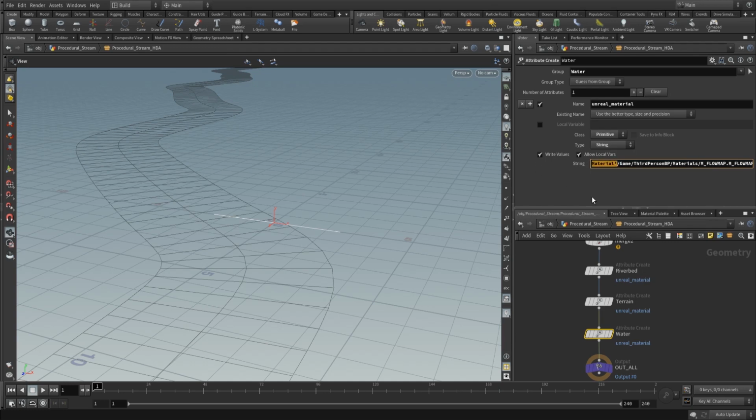I'm going to delete the first part. It's called material. Delete the last tip. And now this geometry that gets created here gets automatically assigned to the right material, which is a really convenient thing for us, since eventually we will be working and creating the material on the go, and we'll be adjusting it. And this way, it automatically updates whenever we update our tool.